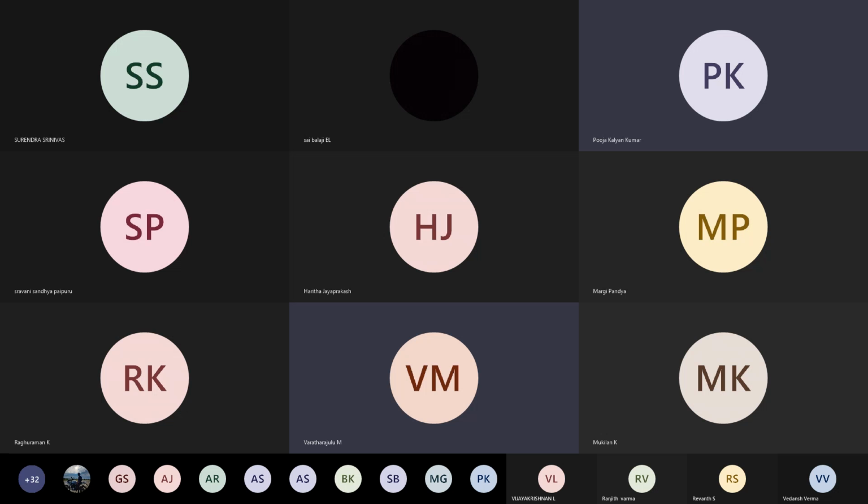The next is the match plate pattern. In this, there is a runner and a gate system mounted on a wooden or metal board, which is called a match plate. That's why it's known as the match plate pattern. Then it's arranged with the cope and drag. This is much easier because the mold can be withdrawn easily.